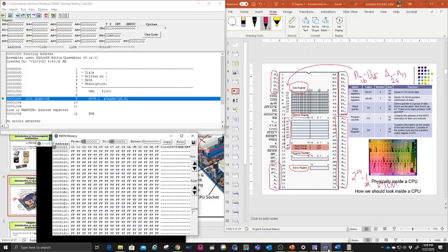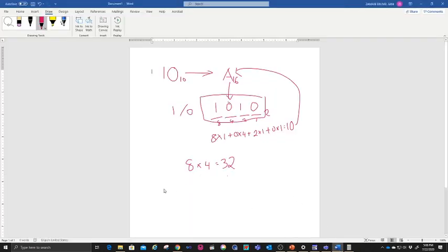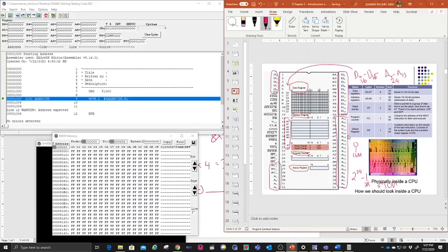So I'm going to repeat that. It means that the total size of memory will be from 0 to 16 megabyte. If you put it using hexa numbers, it will be from 0, 0, 0, 0, 0, 0, up to the final number, which will be F, F, F, F, F, F. So this is the total memory that your CPU can access because of the limitations of the address pin. The address pin is not the same as the address register. So you have to remember that.